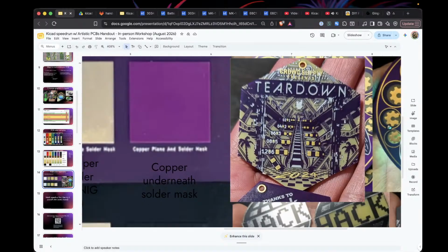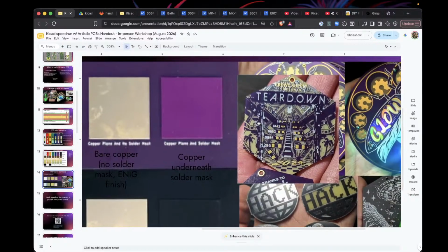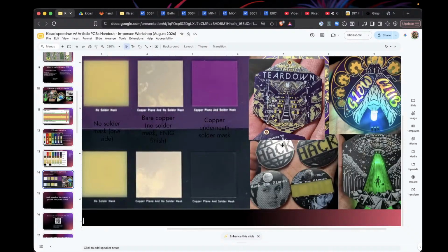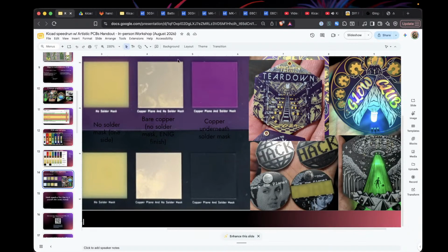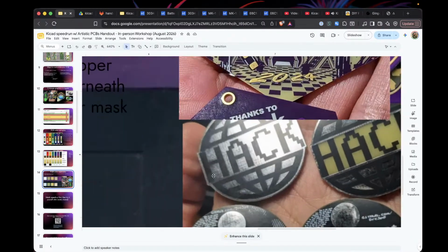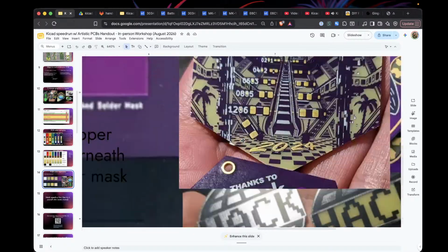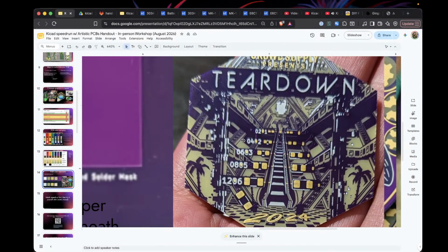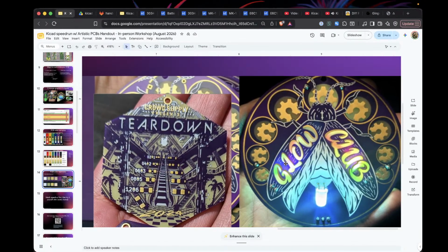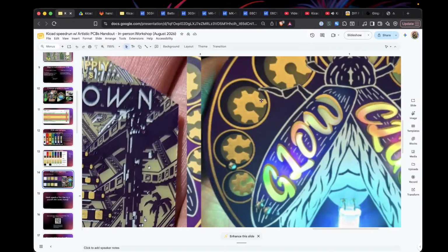Did they dye the gold wiring? The what? Just the gold wiring and the underlying. There are only a couple of things you can do. This is the bare copper. They can do a silver finish on it. I use a lead-free finish on mine because I'm adamant about providing things that don't poison people with lead. We'll say it that way. You can also do an ENIG finish, which is a gold-plated finish, and that's what's on these.